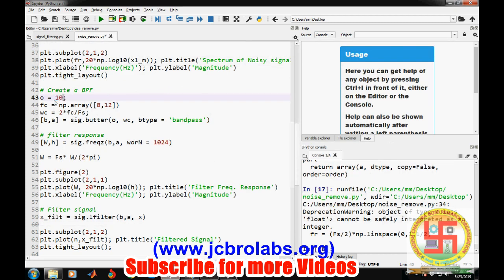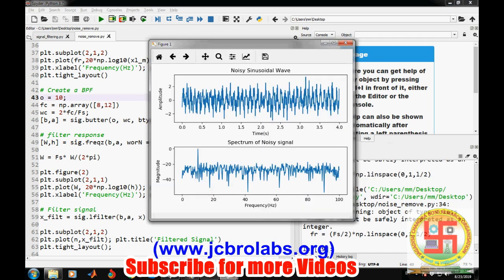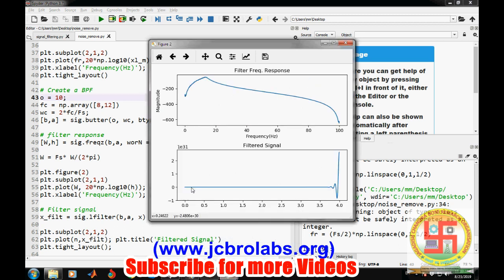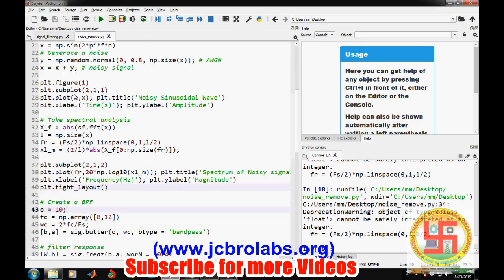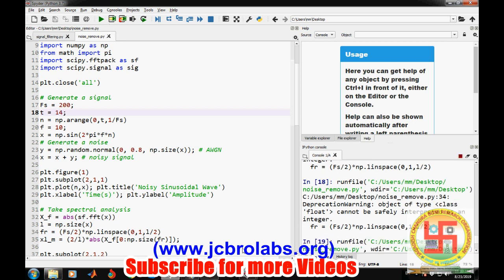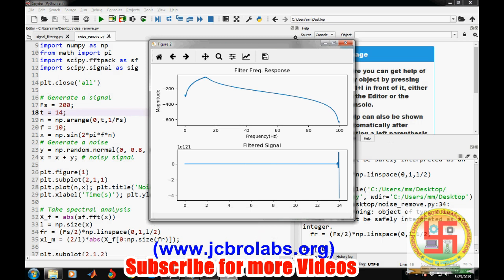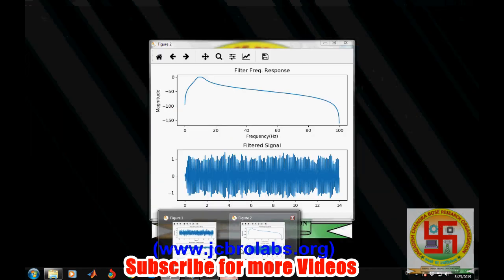So if we try to increase the filter order, let's say 10, because this is an IIR Butterworth filter, sometimes it becomes unstable, or not exactly unstable. We need to increase, let's say, the sample length. If we increase to 14, yeah, it is becoming unstable for filter order 10. So it has to be taken care of while designing these filters, like what should be the sufficient order of the filter. Let's say we are taking a 2, so it is a second order filter.